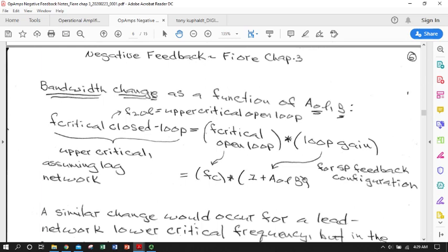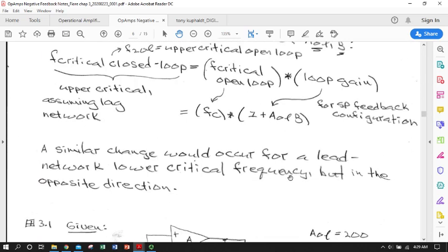You will see this sacrifice factor or loop gain factor repeated again and again in the derivations and formulas for the effects of any particular negative feedback loop on the closed loop properties versus the open loop properties of the circuit. So you'll see that you will either multiply or divide by the loop gain, otherwise known as sacrifice factor, to relate most of those.